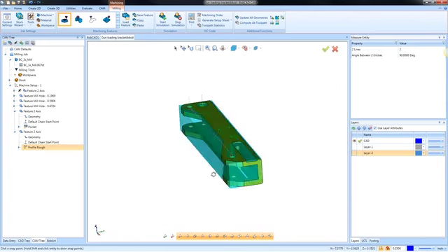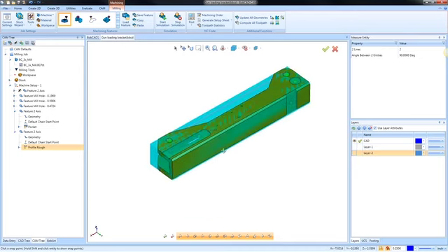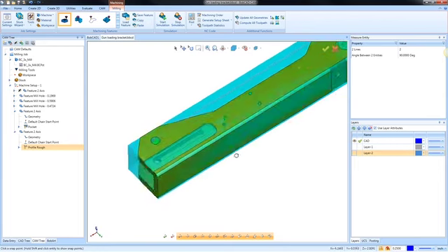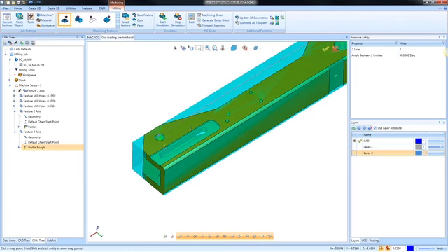All right, the next thing I want to look at is these sections over here. I got about 10 minutes left, a lot to cover at one time. But in this section here, I want to use this same type of routine, this helical milling, but instead of for the holes, I want to use it for these slots over here.